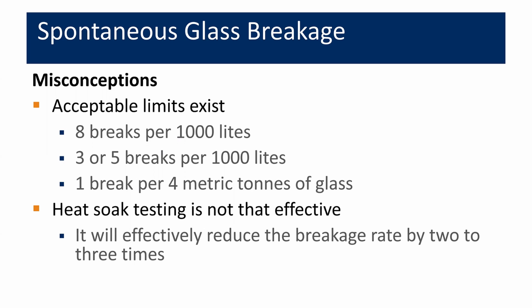And then the last misconception is that heat soak testing is not that effective. You can see by misinterpreting those acceptable limits up above that people have indicated, and manufacturers even have this on their published literature on the web, that it effectively reduces the breakage rate by 2 to 3 times. And they're misusing the 8 breaks per 1,000 and the 3 and 5 breaks per 1,000 to indicate that reduction.